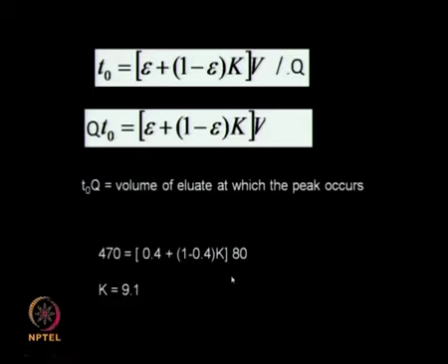So this K is nothing but the linear adsorption isotherm constant, which relates the concentration of the solute in the stationary phase to the concentration of the solute in the mobile phase. If you remember, q equal to K into C, where q is the concentration of the solute in the stationary phase and C is the concentration of the solute in the mobile phase.